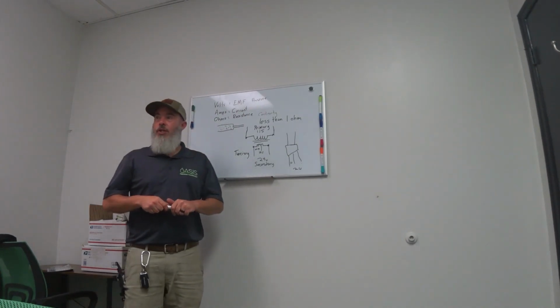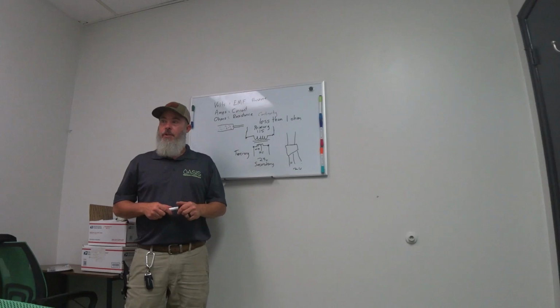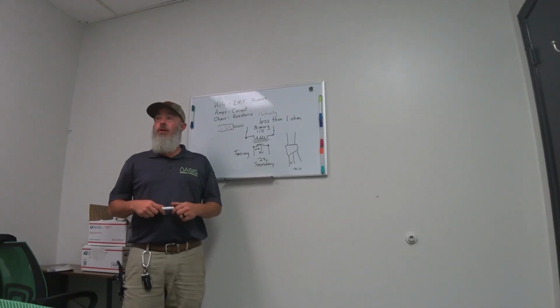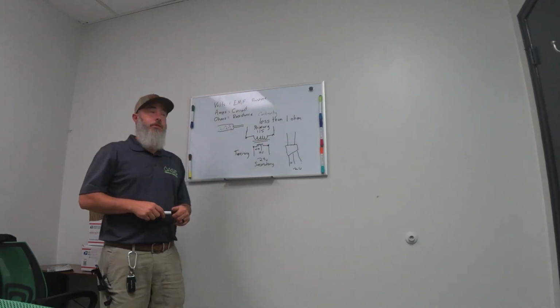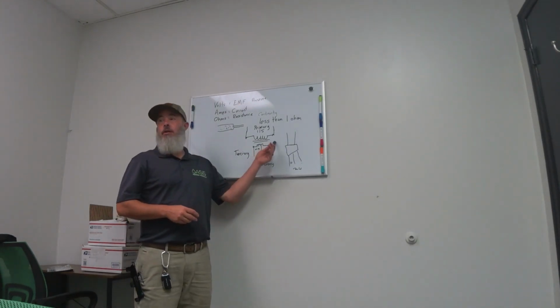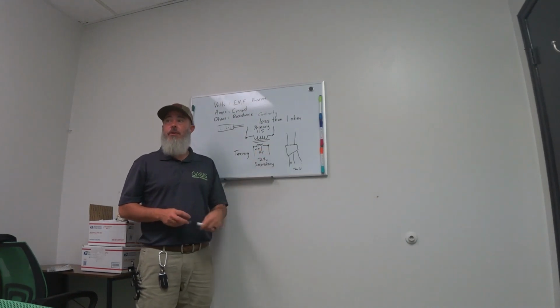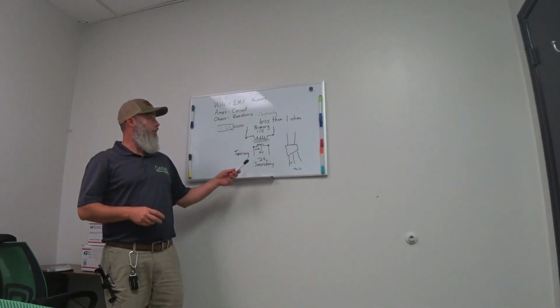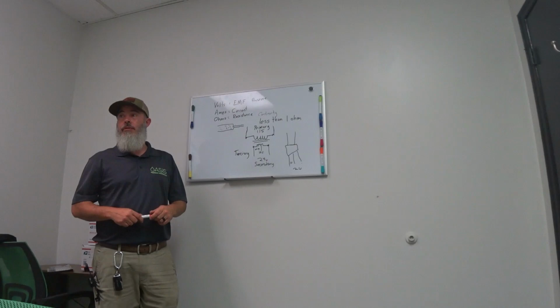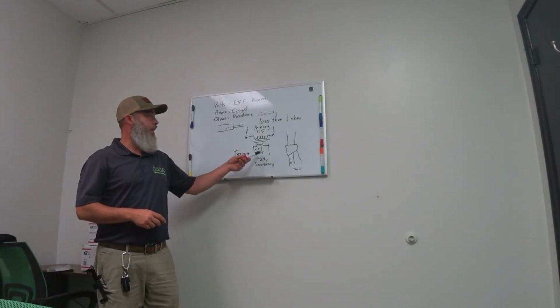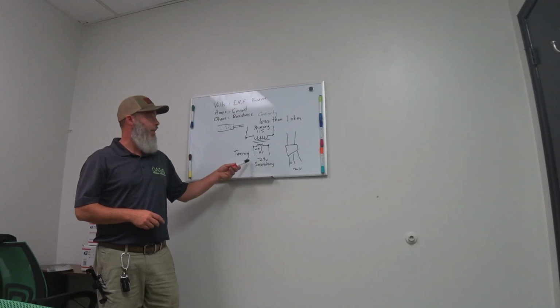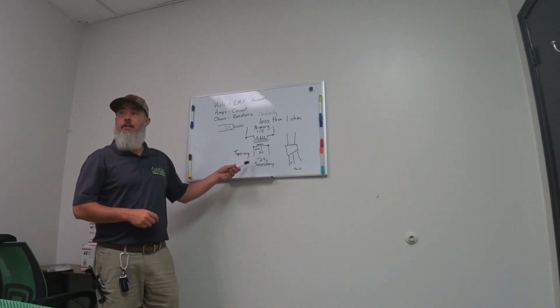When you're troubleshooting with somebody on the phone, you ask, what are you getting on the primary side of your transformer? You're going to want that 115 volts. Okay, well, now what are you getting on your secondary voltage? What do you have going to the board? This 10.5 volts, we know that it's there specifically to power the board.